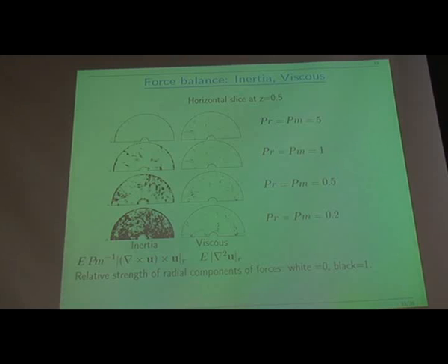So in your scheme, do you have numerical constraints on the time step? The constraint comes from the predictor corrector. The predictor corrector tells you whether you're resolving things in time correctly. That is set automatically by the code, and it gives values around 10 to the minus 5 or 10 to the minus 6 of the diffusion time. So to run a full diffusion time, you've got to take between 100,000 steps and 1 million time steps before you're fully resolved.